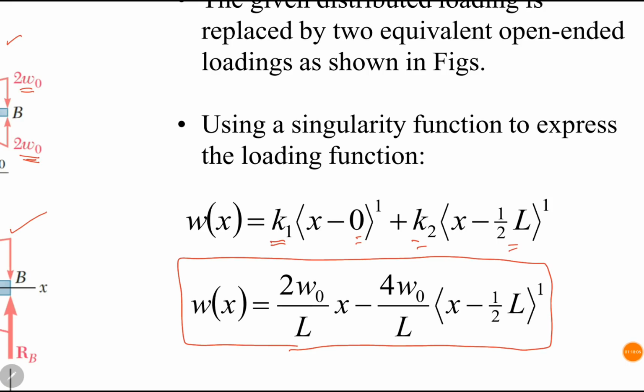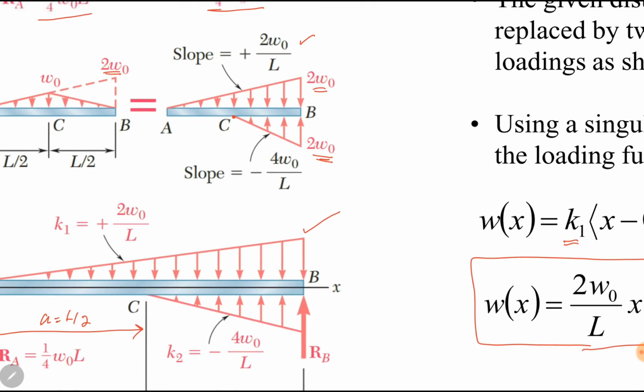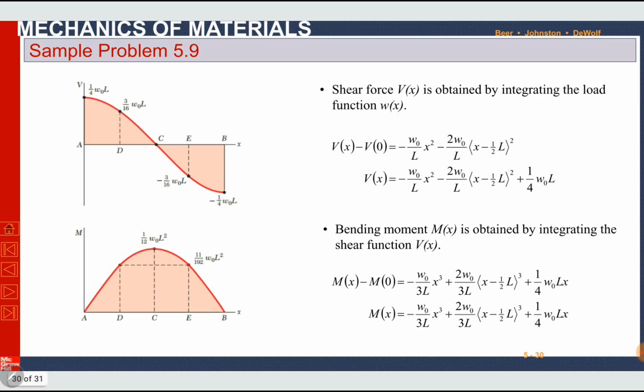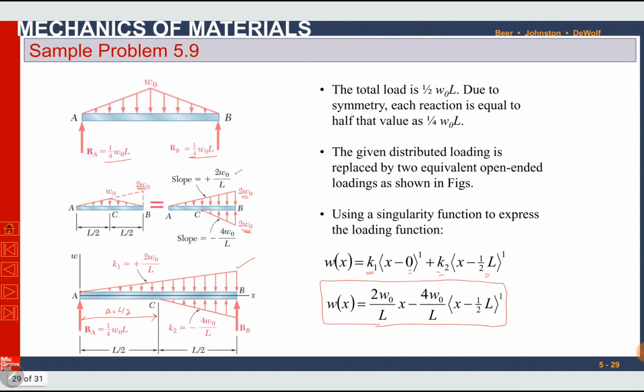Remember that load function is written for distributed loads only. Either uniform distribution or linear distribution or quadratic or whatever the distribution is. Next is shear force function. So remember that for shear force and bending moment, we will always start from the left end, and the load or moment at the left end is the initial condition.